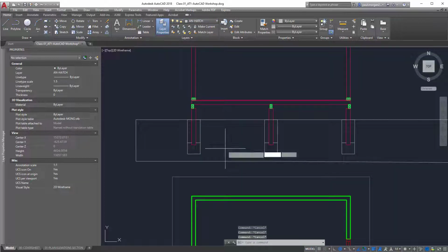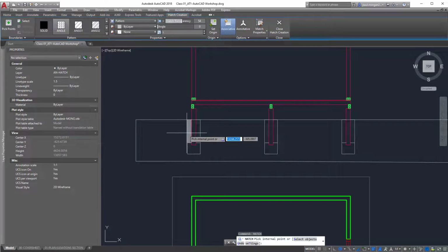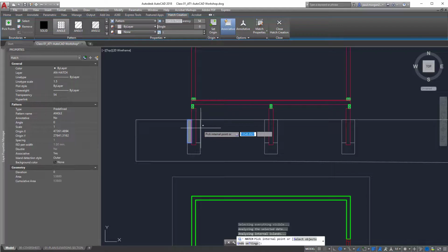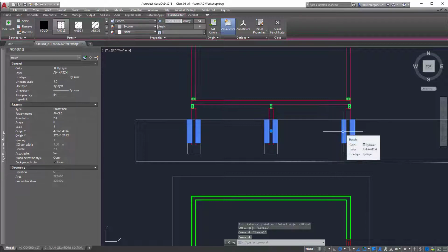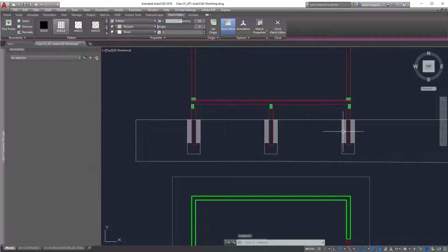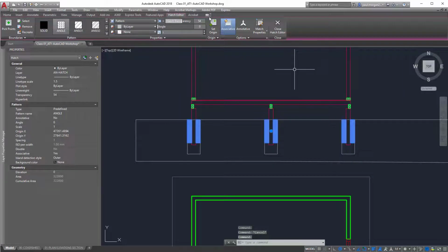And another good tip for you is just start clicking straight away into zones. So I'm just going to click in this zone and in this zone, because they're going to be the same hatch. It's going to be that backfill hatch, and the same thing in these stumps as well. So however many times I click within this one command, once I hit escape, you'll see that all 3 of those stumps or 6 of those zones select as one object. It's always much safer just to select the elements you want, hit escape, then come back and click on them to then edit them.